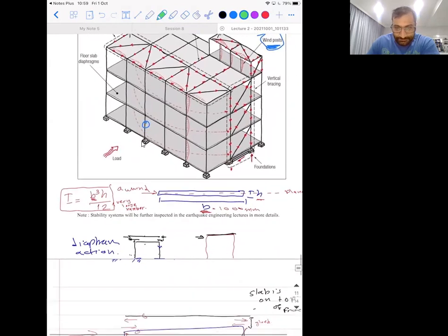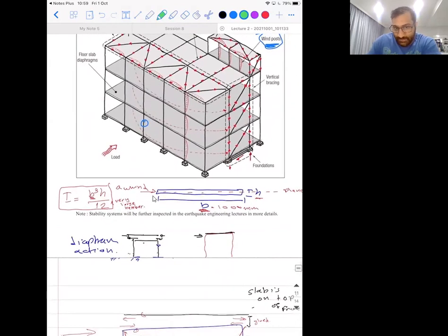I've written it down. So if wind hits it, it's not going to deform this surface much. So what happens is it transfers, yeah, very large, as we said. This is the plane, this is H, the thickness, B, width. We have diaphragm action, which means that the slab, the black line on top, sitting on the frame, would transfer the load, because it's not deforming, because of its large inertia, to the frame itself. Simple concept. It's not very simple, but it's graspable.